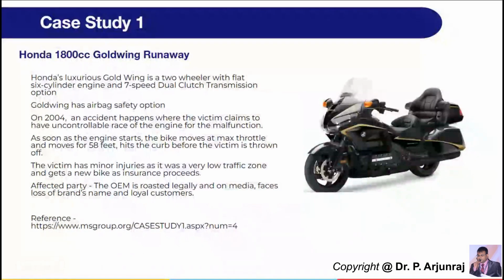I can also give one more example where you have the motor reversing issue. Normally, when you apply forward acceleration, sometimes because of the reverse motor, the vehicle goes in the reverse way instead of forward. Even these are some of the failures that happen in some vehicle applications. All these are part of safety issues, where the OEM has to predict all these things and develop the vehicles in such a way that when you're going forward, the vehicle should not go reverse.